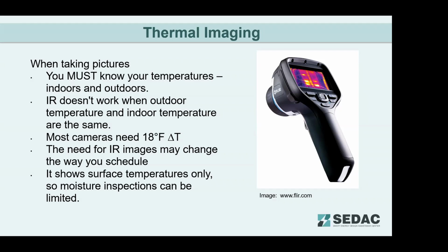And in certain jobs where that infrared inspection was so important, we've actually scheduled around weather, or rescheduled around weather if it turns out it was going to be too temperate that day. So from an infrared point of view, I like hot and cold weather, not nice 70-degree weather. If I'm off for the day, I'd rather have a nice day. But if I'm working, I actually want those extreme temperatures.